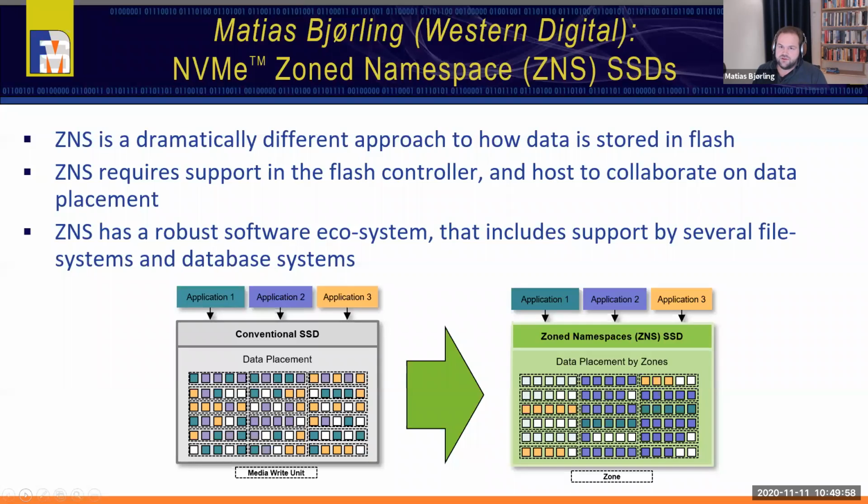What it does is it's a new way for the host and the SSD to collaborate on data placement. The idea is that in a conventional SSD, when you write data onto it, the SSD may write data from different applications into a single block, which is a gigabyte large, which means you have random data going into it. Ultimately it's a log-structured approach where you need garbage collection. On SSDs, this garbage collection is handled within the SSD.